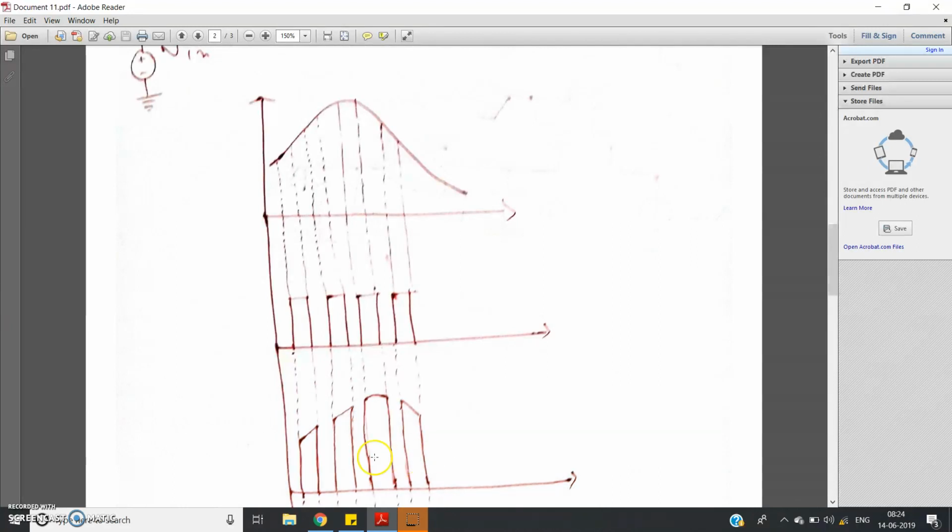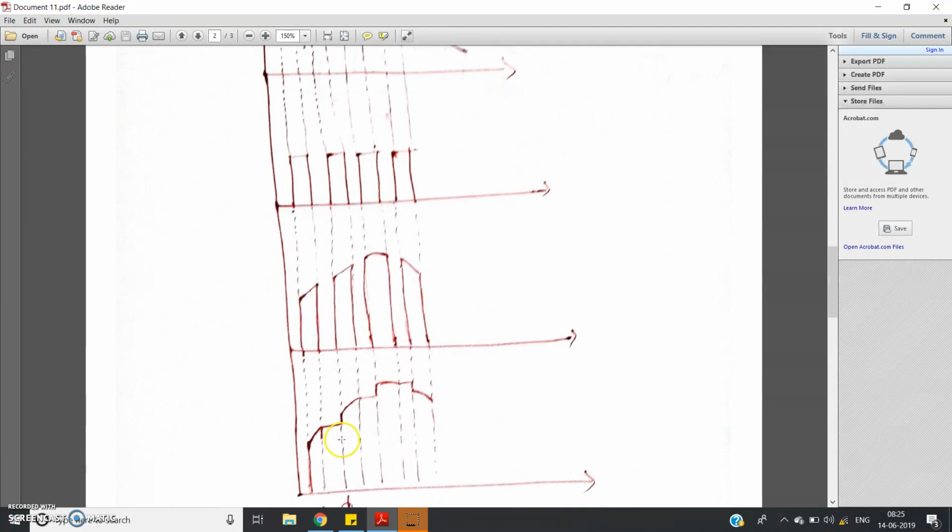So this is from the basic idea of communication engineering, you can say that this is how sampling we can do. But see, this sampling pattern, when the control voltage or gate voltage for this particular NMOS switch is VDD, then input is passed to the output. But when the gate voltage is 0, the output is going to 0 volt. But suppose you want to hold that particular voltage. Suppose when the control voltage or gate voltage is 0, you want to keep your output voltage as this voltage only. That is, suppose you want to make this kind of waveform. See how this waveform looks like.